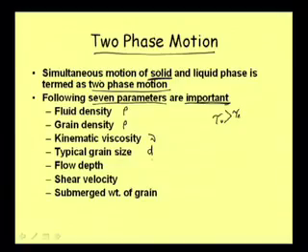We are considering this as typical, and right at this moment we can consider this as d50 of the particular size, or from the analysis of what we are getting from the field, we can take d50. Then flow depth h is also influencing the erosion. Then shear velocity u star. This is a very important element.